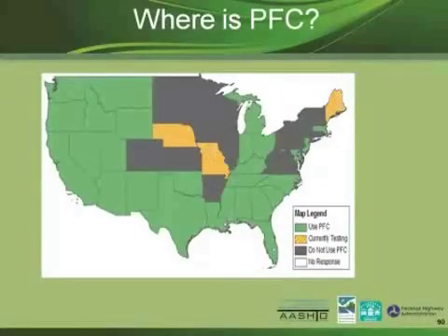Next one. So you're probably thinking, well, we don't have PFC here, but in fact, except if you're in the upper Midwest or parts of the Northeast, you actually do, all around the West Coast and through the South, even up through Michigan. And some of the concerns early on about porous pavements were really about freeze-thaw and will it fall apart. And Indiana did a recent 5-year study and found that after 5 years, basically the condition was the same as conventional pavement, which led to both them and Ohio adopting it, and Michigan's adopted it too. So it's actually a widespread material included in standard specs in the majority of states. Next.